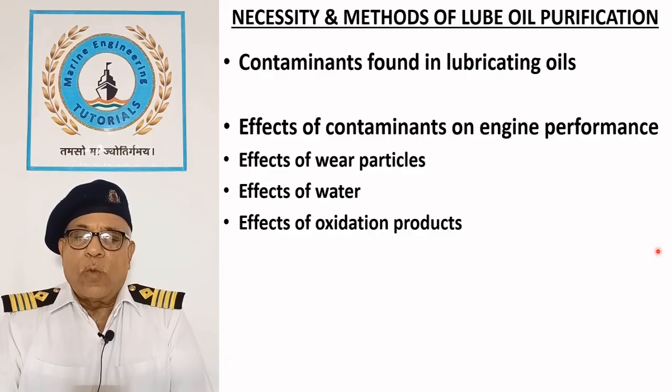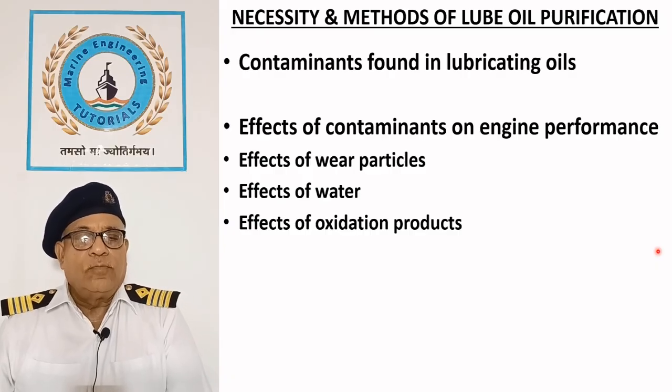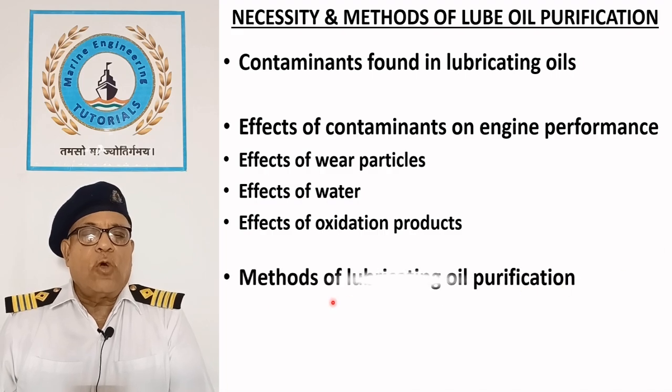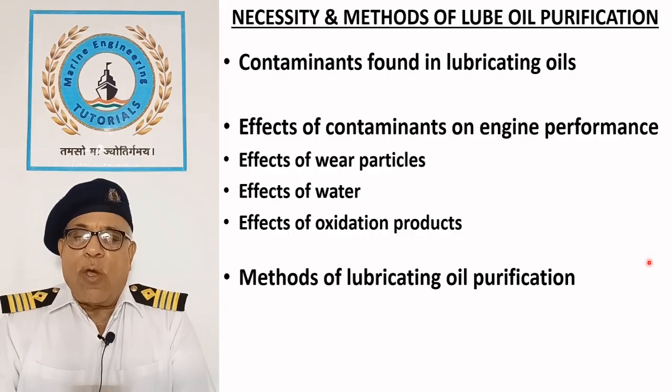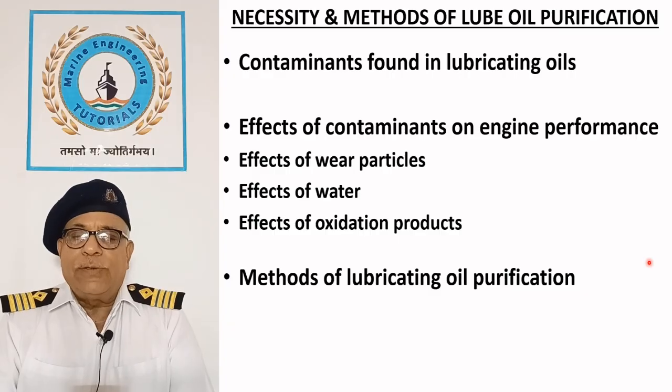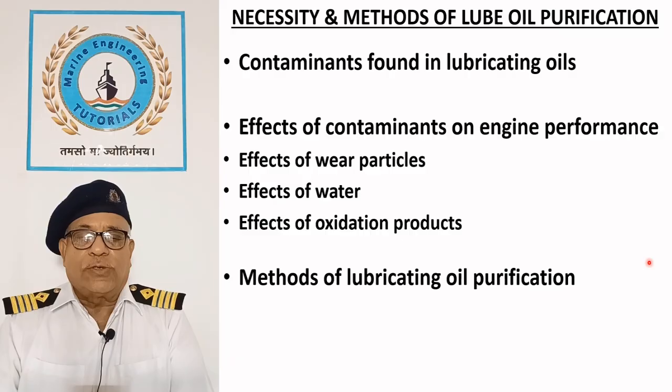Oxidation of oil also forms acids which start the corrosive cycle and shorten the life of oil, resulting in increased frequency of oil replacement. Methods of lubricating oil purification. Treatment of lubricating oil is carried out both by centrifugal separation and filtration, which improves engine performance and its reliability. It also increases the service life of lubricating oil and reduces the operational cost.